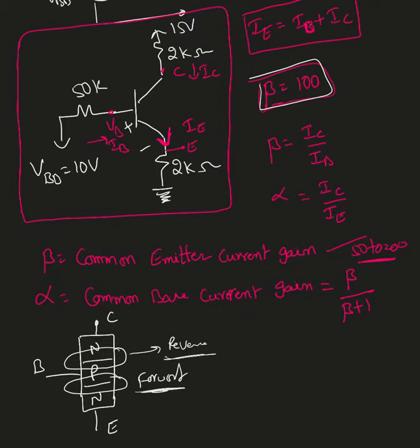So in saturation mode, the beta value does not work. I mean, it doesn't have any value. We'll have a new beta value which is going to be beta forced.